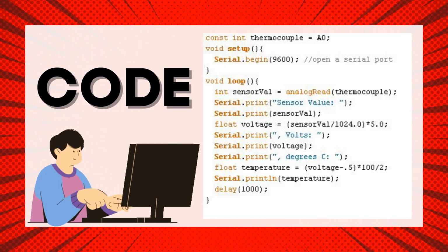So that is the TMP36 sensor output, as we have already said, 0 to 5 volts, stored in the voltage variable. The float data type differs from integer data types as it accepts any number with decimal points. This voltage will be shown in your serial monitor using the Serial.print command. In order to get the actual temperature reading, multiply the voltage reading by 50 and use the Serial.print command to display the temperature value in the serial monitor.